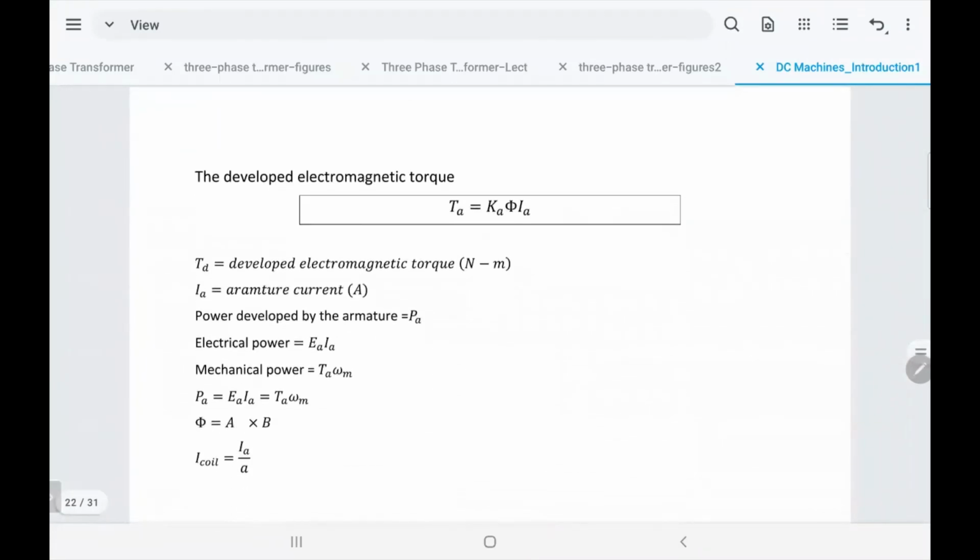Well, the variable in the machine is the mechanical variable, the torque. The torque depends on the magnetic field and the current. Don't you observe that the two equations that I started with in this lecture are very similar to this one? You remember in the beginning of the lecture, I said the force depends on BLI and the voltage depends on BLV. It's just the same.